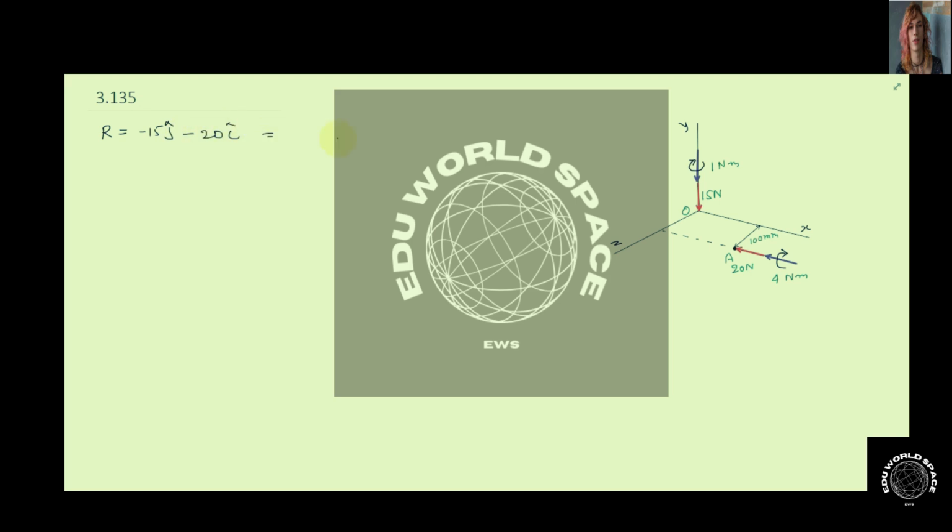So the equivalent force comes out to be minus 20 i cap minus 15 j cap. If you want to find the magnitude of the equivalent force, it will be the square root of minus 20 whole square plus minus 15 whole square. So it comes out to be 25 Newton.